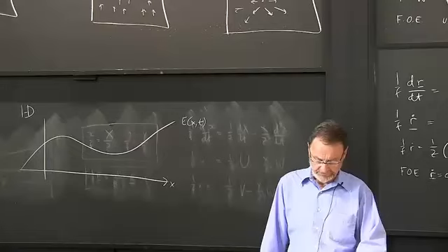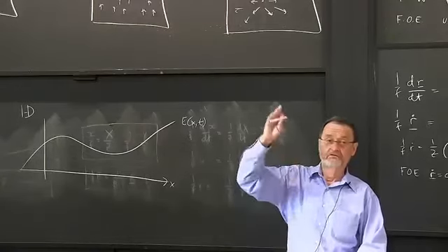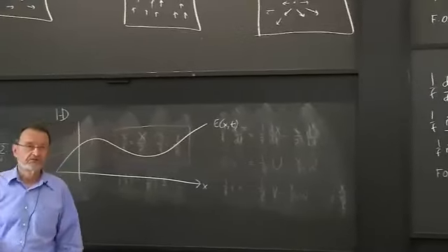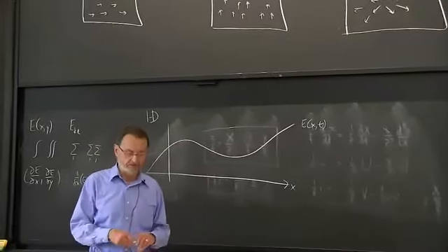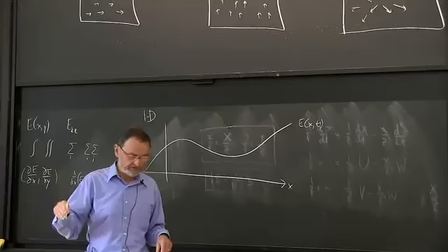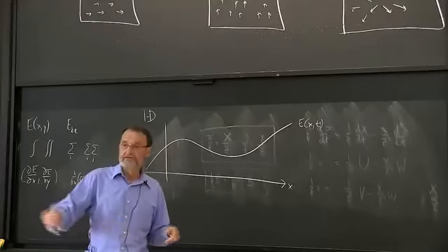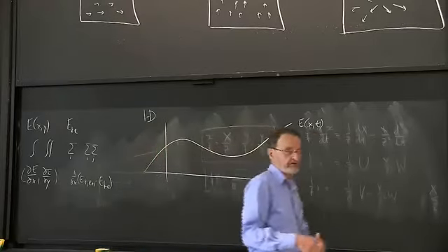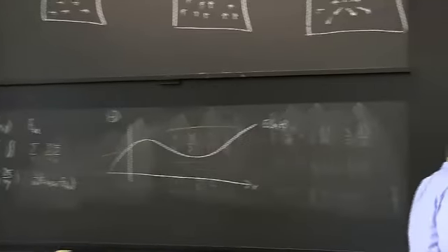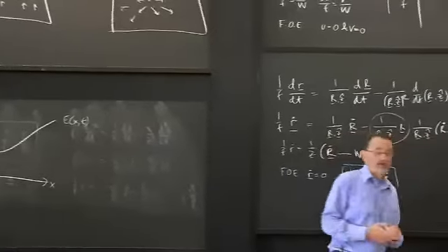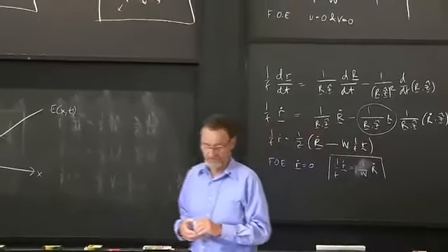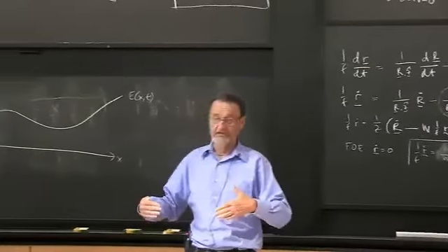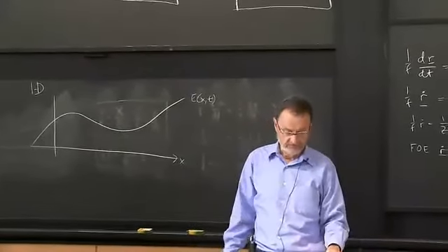And the disadvantage of a linear sensor is that to get a real image, you need to scan it. This is done quite a lot in industry where things are moving along on a conveyor belt, and you can use a relatively cheap, very high resolution linear array sensor, and the conveyor belt motion provides the other dimension of the image. It's also used in satellite imaging where very high quality 1D sensors are used, and then the motion of the satellite provides the scanning to produce an image.